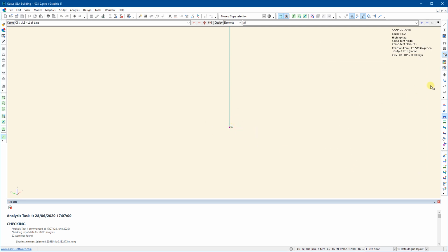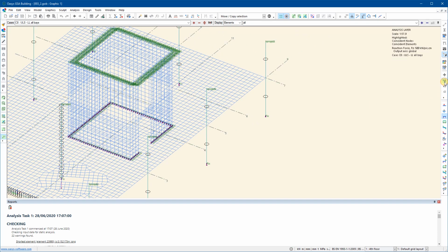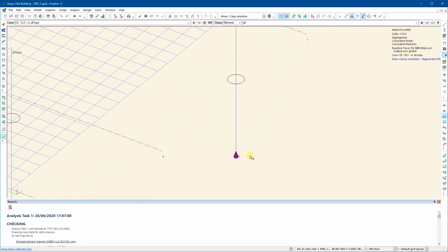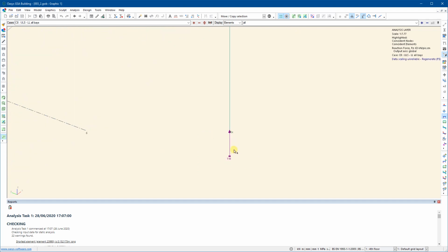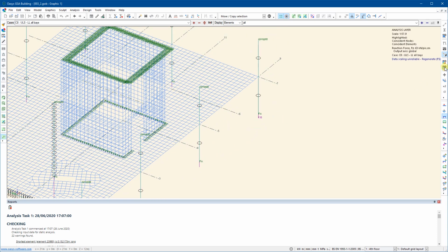it's very small. So I could use the times or division to change the scale. You can automatically get GSA to rescale the results by pressing the diagramming button that you see there. And if I do that, it should, I had hoped, have rescaled it, perhaps just because I'm zoomed in too closely. Of course, maybe it's a very small value. If I do ×2 a few times, and I annotate that, again, it's given me the actual value itself. So again, that's one way to look at the results. You can use these diagramming tools.